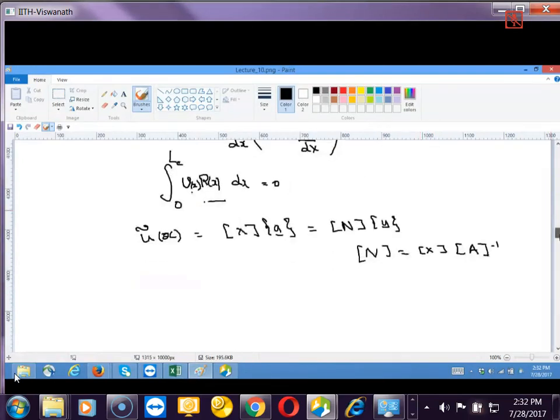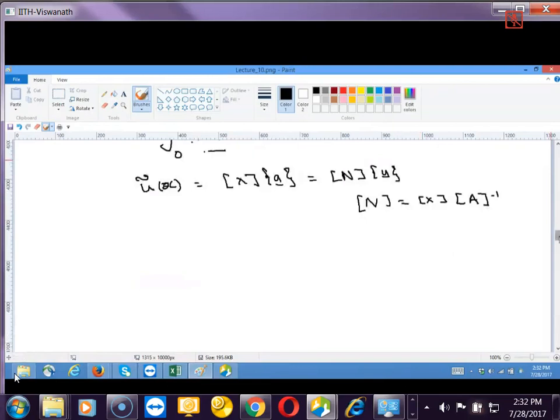So this formulation is valid for all the cases. Now if this is u tilde, let's calculate strain. Strain is nothing but du tilde by dx. The du tilde by dx you can write also as summation of Ni ui, I from 1 to small n, where n is the number of nodes per element.